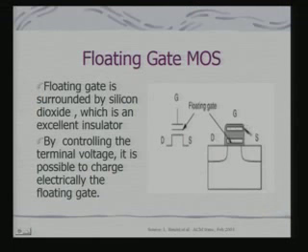So, what is the basic technology that goes into them? The concept is that of floating gate MOS, and it is effectively a single transistor. Just like in DRAM we use a capacitance to store charge as indicative of the data, the same thing is true here as well. All these modern EEPROM and flash memories are built around this technology. There is an additional floating gate in these transistors, surrounded by silicon dioxide, which is an excellent insulator.